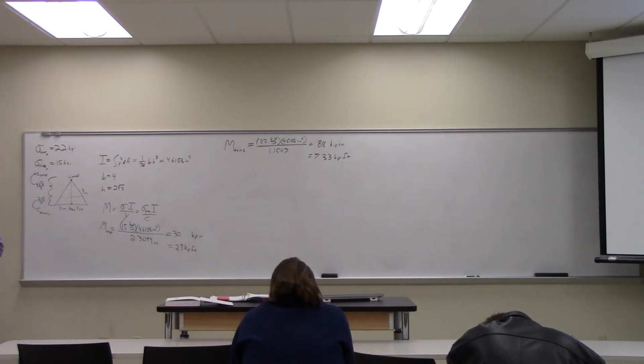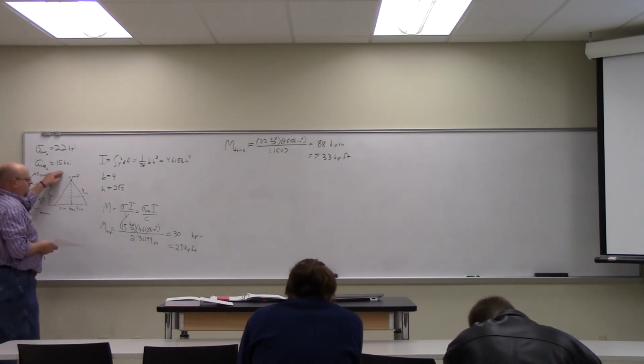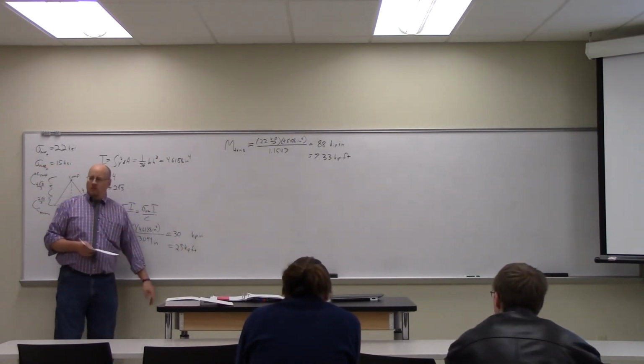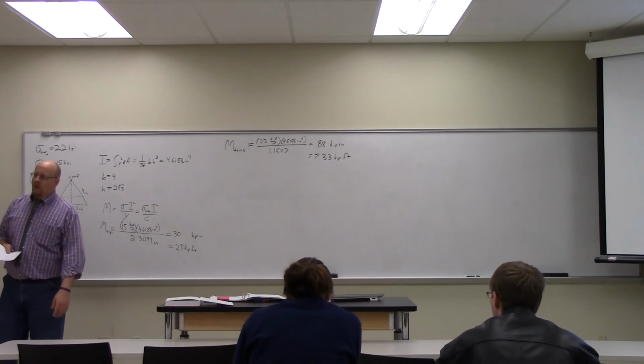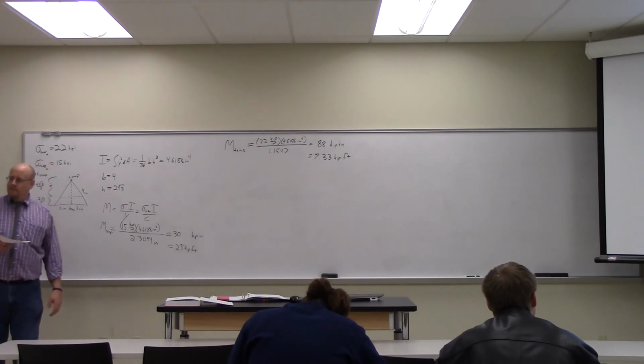So, how's it going to fail? It's going to fail in compression. Because to reach failure, I need only 2.5 kip feet in compression as opposed to needing 7.33 kip feet in tension. So the answer to the question would be what? 2.5 kip feet.